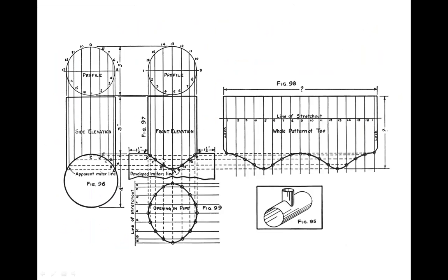So a vertical pipe is to be welded to the horizontal pipe. So this is that diagram. So it is not easy to cut this pipe in this way. Cut करून नाही येणार आहे. It is not possible. So for that, for this pipe development is drawn, the sheet is cut in this manner, rolled, and after that this pipe is placed on the horizontal pipe, and then welding is done. So this figure is showing you the application of the development of the surfaces, where exactly this development is required.